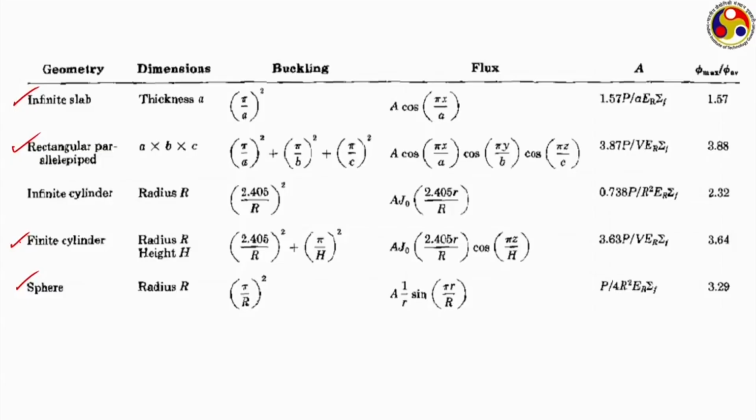Same for an infinite cylinder or even a finite cylinder. If we know the values of R and H, still we need to put the assumption of axisymmetry, and then only shall we be able to analyze this finite cylinder following a 2-dimensional cylindrical coordinate method.